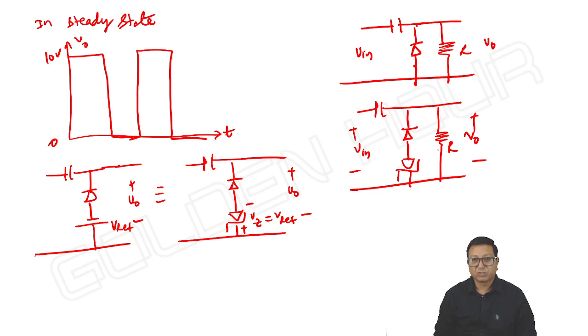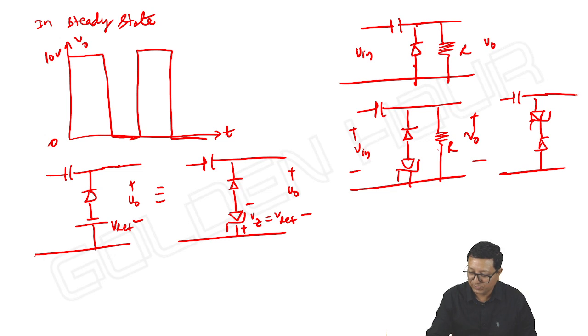Okay, with positive clamper, the diode and Zener diode, whether it's a positive or negative clamper, both should be in opposite directions. Even to confuse us, they may show the Zener diode like this and the ordinary diode upwards this way. Doesn't matter, both are in series, nothing to worry.